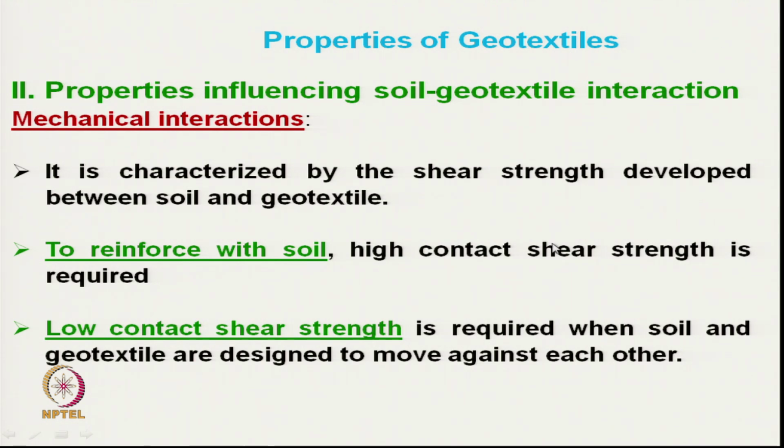In some applications, low contact shear strengths are required when soil and geotextile are designed to move against each other. So, there are different applications, and depending on that we can select the fiber, fabrics and the type of soil.